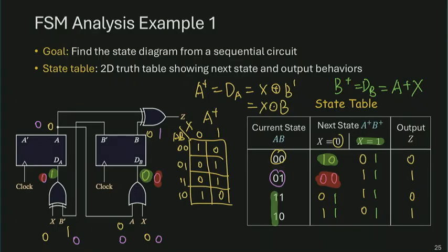To sum it up, we have two methods. Number 1 runs through simulation, plugging in all these numbers. Method number 2 is to analyze the Boolean expression over here and, knowing its relationship with respect to my next state behavior, directly fill out the next state column for A, which happens over here, and the next state column for B, which happens over here, based on those Boolean expressions.